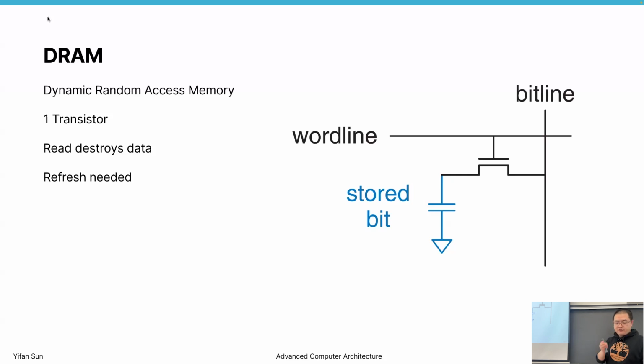No, not really a PCIe, but for your motherboard, you plug into the motherboard that has DRAM. There are actually many chips on it, right? So they're typically carefully scheduled so that one chip is refreshing while the other chip is not refreshing. So other parts of the calculation can continue going on, to prevent a global hiccup. If there's a hiccup, even when you move your mouse, you will feel that it's not moving. If you click something, sometimes it will not respond to your user interaction, which is not tolerable for a computer system.